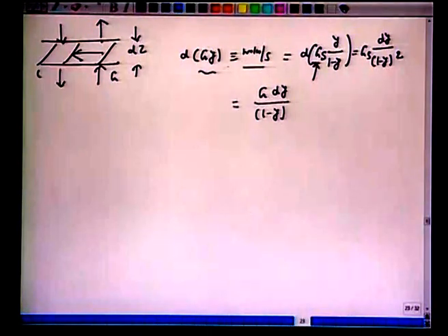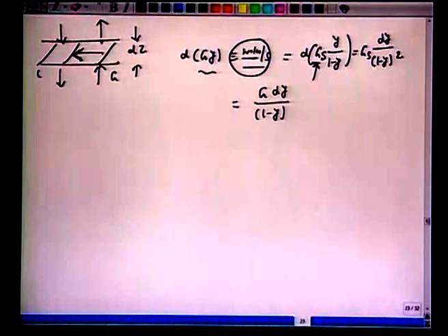What is the concentration? Let us go over once again. In 1 second, so many moles of sulfur dioxide change across this dz. Why? It is getting absorbed in water. So, dGy equals d(Gs y over 1 minus y). Gs is constant, does not change along the column, so Gs is outside the differential. You can obtain Gs dy by 1 minus y square. You can go back and write Gs over 1 minus y as G, so we have G over 1 minus y. That is the species balance we have made in the gas phase.